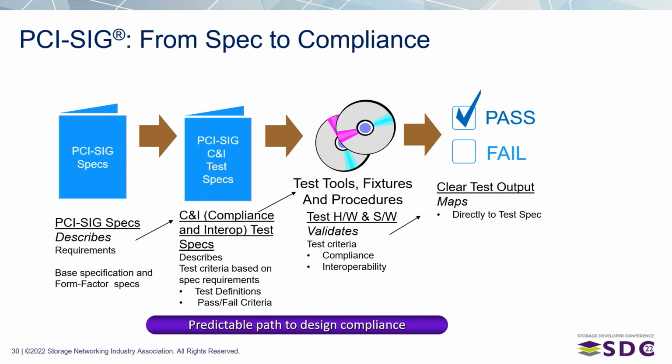As we all know, any successful standard needs a well-defined, robust compliance program, because if you have parts that are out there for 2 decades, and a 900-member company consortium developing technologies based on a standard, how do you make sure that they all interoperate with each other? One of the means is to come to a compliance workshop and get your part tested for compliance. So we have an extensive compliance test suite that covers everything from electrical signaling to the link layer, are you doing the replay properly or not, to the transaction layer, to the configuration register. So it's a fairly well-defined compliance mechanism that we go through in the compliance test suite.